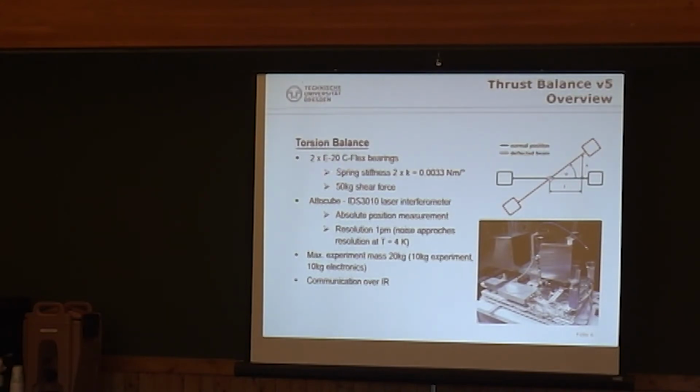But we chose this bearing so we can put a lot of shear force on the bearing, because if we put the EM drive on the experiment box, it will apply a shear force to the bearing, and this can actually damage the pivot. We actually damaged a previous one that could not withstand the high shear forces.